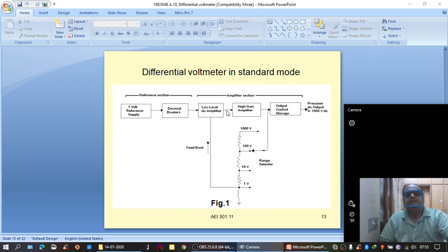As a result, some error would be generated, positive error. That positive error is amplified. Because of that amplified positive error, the voltage at the potentiometer increases to be A into V1 plus E1 plus delta E or delta V. So obviously the drop across this also increases now. As a result, what happens here? The difference between these two will come down.